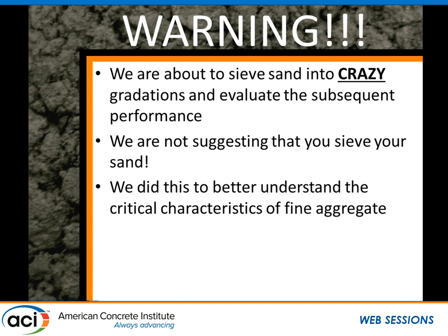I have to warn you, what I'm about to show you is a little crazy. We're going to sieve sand. And you'd say, what? You will never sieve sand. That's so impractical. But our goal is to try to learn what's important. Our goal is to try to control these sand sources, to see what's critical and what's not. And sieving is the best way to get there. So we did this to better understand the critical characteristics of the fine aggregate. And I am not suggesting that you sieve your sand in practice. Okay? I'll try to be a practical guy.